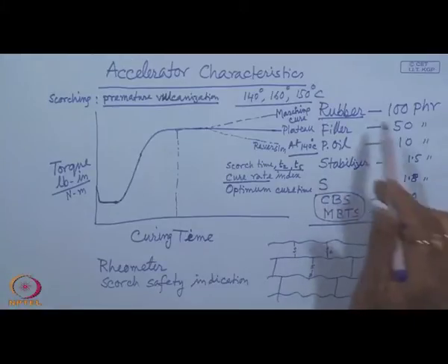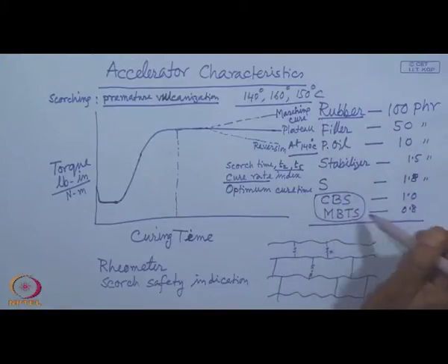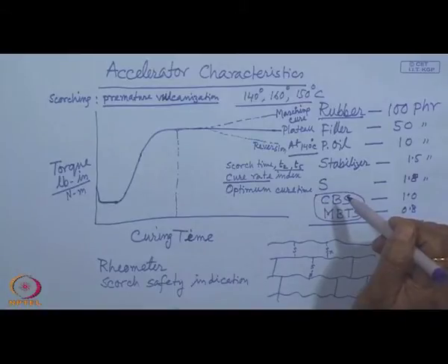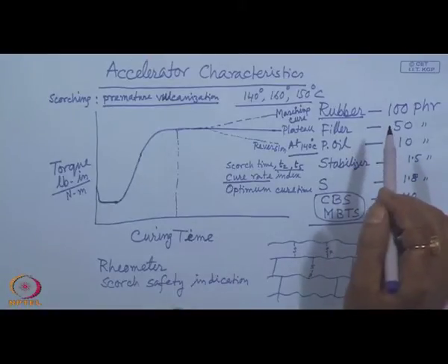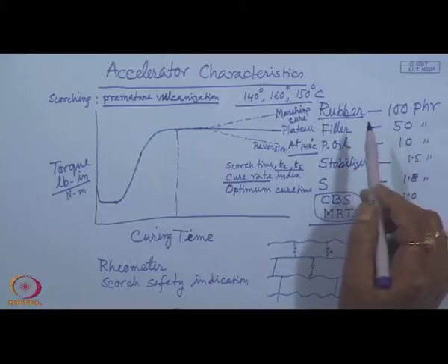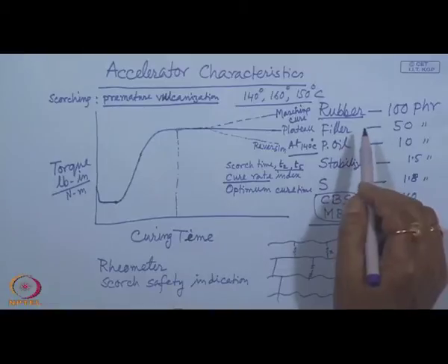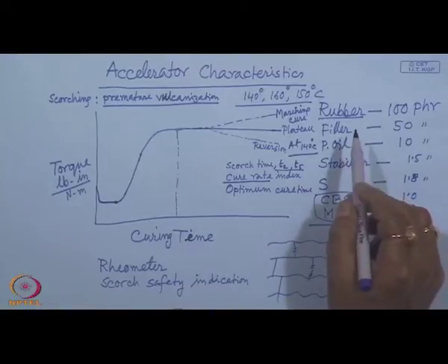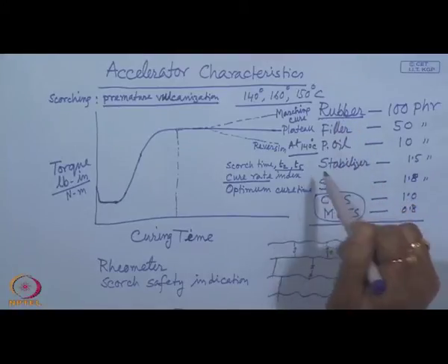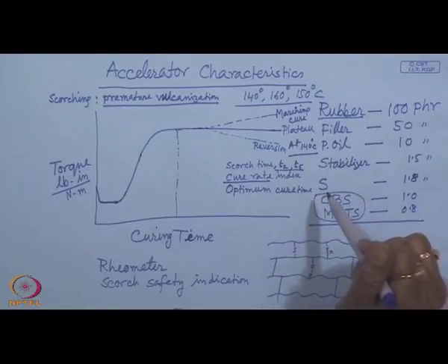Not only that, after compounding, that rubber compound is used for fabrication to give a shape to that product, say making a tire product or making a tube or making a profile. So, that passes through some machineries, say extruder machine or curing mold, curing press, etc. So, during that period, the compound should not start any premature cross linking.